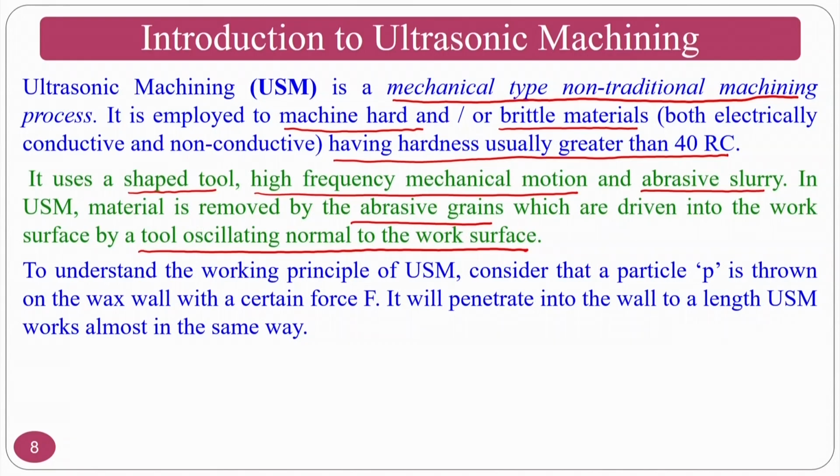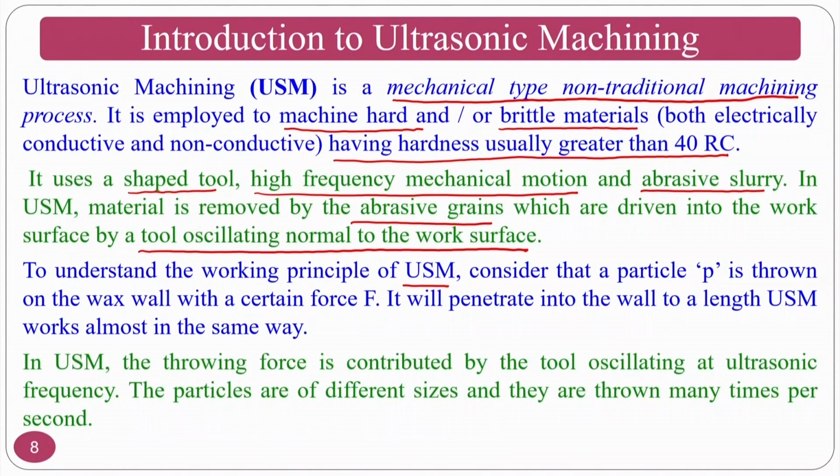To understand the working principle of ultrasonic machining, consider a particle P thrown into a wax wall at a certain force F. It will penetrate into the wall to a certain length, and USM works in a similar way. The throwing force is contributed by the tool oscillating at high frequency. So, there is a wax wall, and you just throw a stone or a particle P. What will happen? It will go and indent into the wall.